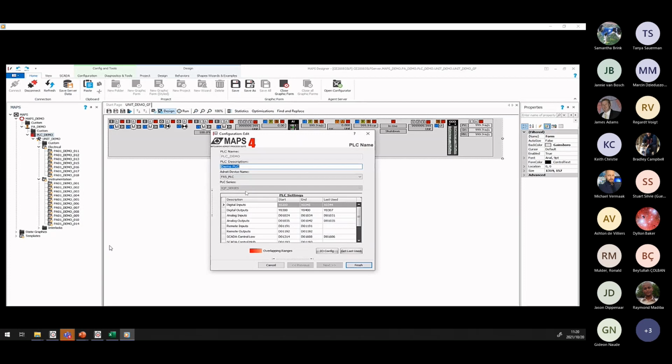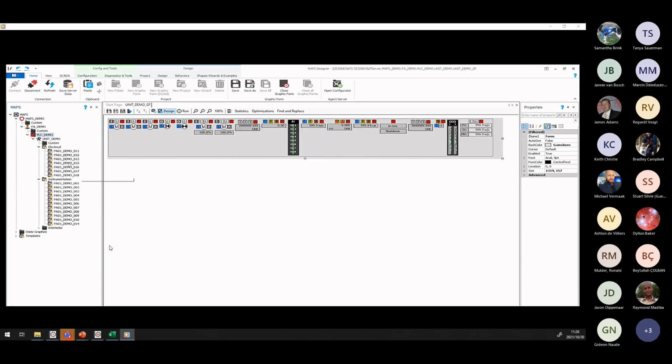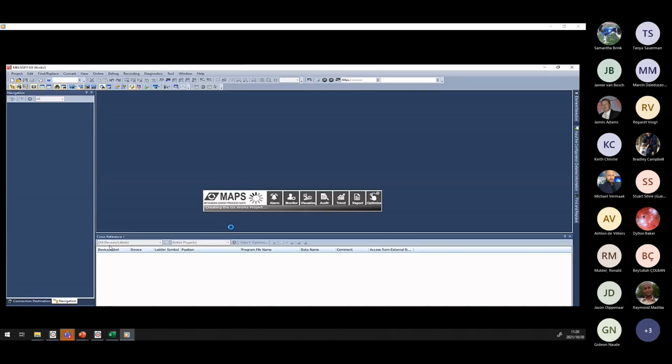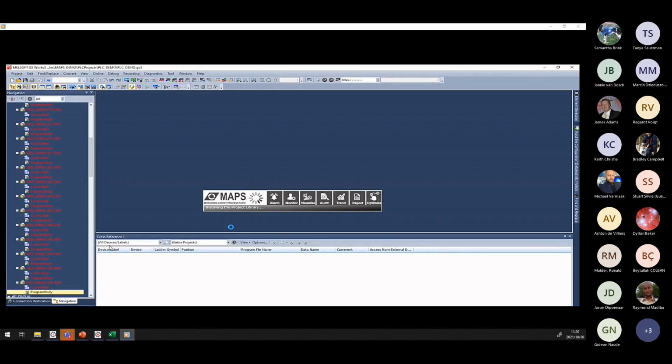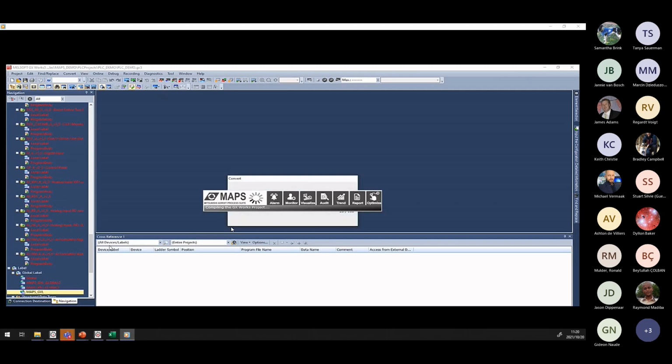There I'm showing you I've got the IQF series selected. So now I'm going to build a PLC project that will build a GX Works3 project for me. That is an IQF selected PLC to use. This process takes normally about 2 or 3 minutes, so I've just cut it out a bit, and we will see what happens now.